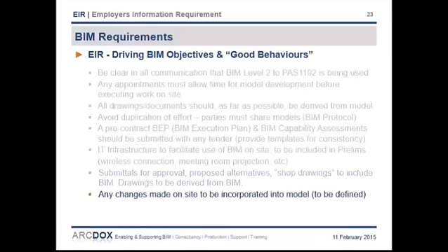Ideally, if you want to get an as-built model at handover, any changes that occur during the installation on site should be recorded back to the model. The importance of this will vary from clients or project types, so the tolerances will have to be defined, but you may, for instance, require a 3D laser scan as proof of installation before closing up works, or you may want the model to be updated according to the scan.